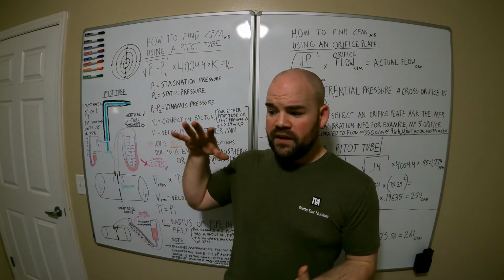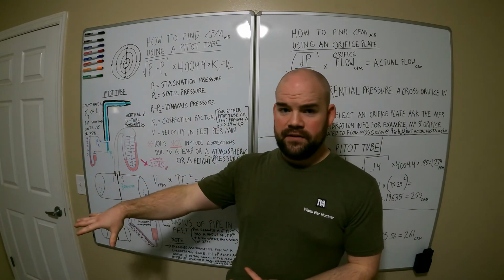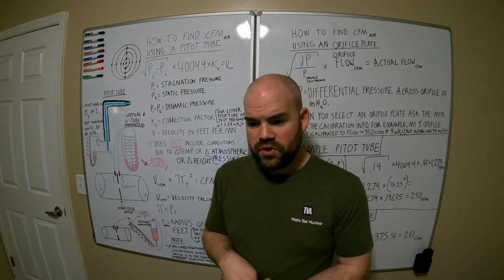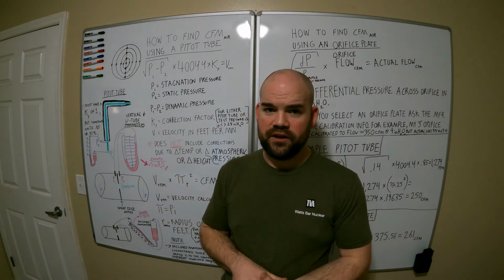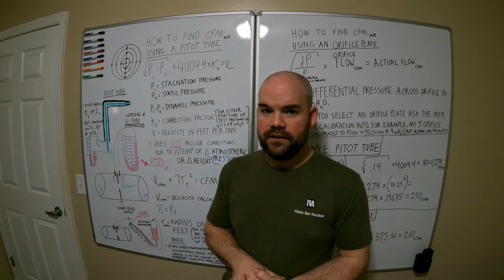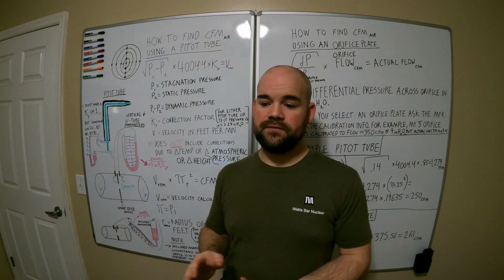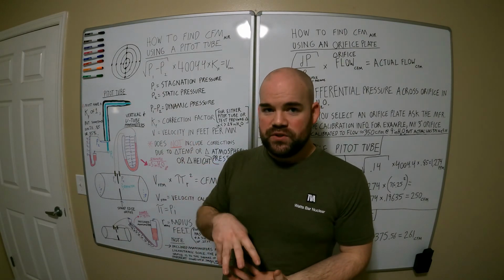But on a roots supercharger, like what I have in Old Red, it's an air mover, okay? It's not a compressor. So when it moves the air, it creates heat. Their adiabatic efficiency is terrible, okay? And look up adiabatic efficiency, but the temperature rise.